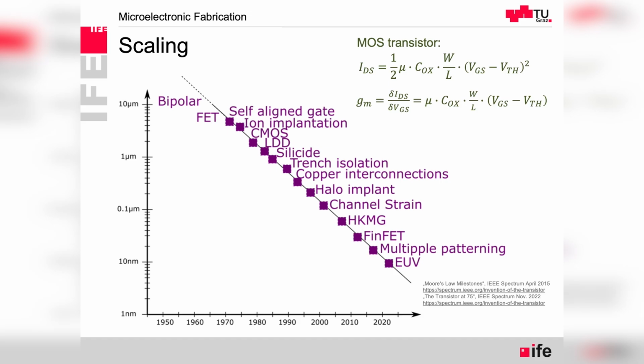But before that was possible, just 2 years ago entering in production, so let's say about 2021, we were able to solve this fine resolving of the pattern of the transistor with over 100 nanometer wavelength of the UV lasers by doing the multiple patterning. So maybe double patterning was done before, but multiple patterning with triple or more was also the new development.